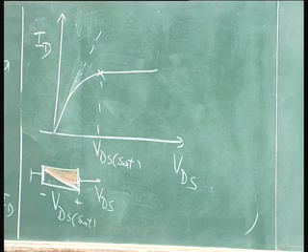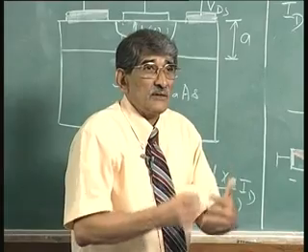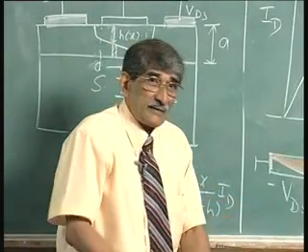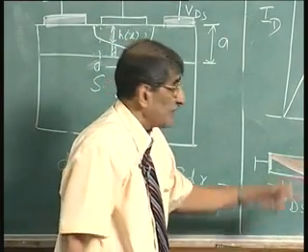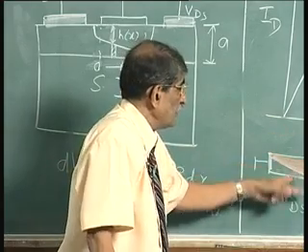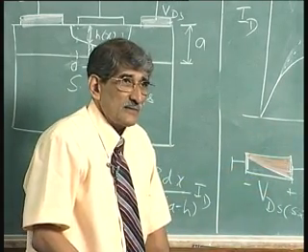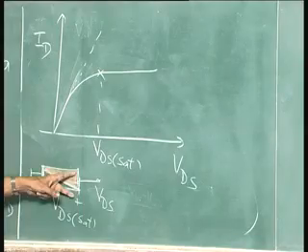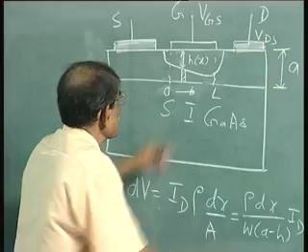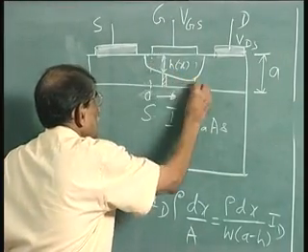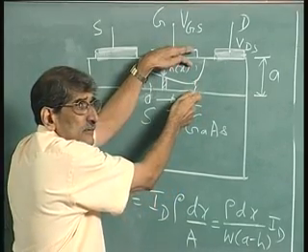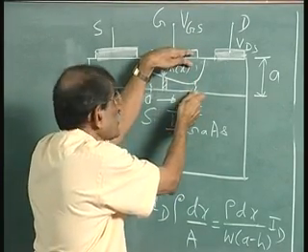We said that V d has saturated; whether it is correct or not we have to examine later. It is quite correct for most devices, and where it fails we will examine afterwards. V d sat is the voltage at which the channel has pinched off at the drain edge. This has closed down this path. Although it cannot close totally, it is almost closing down.